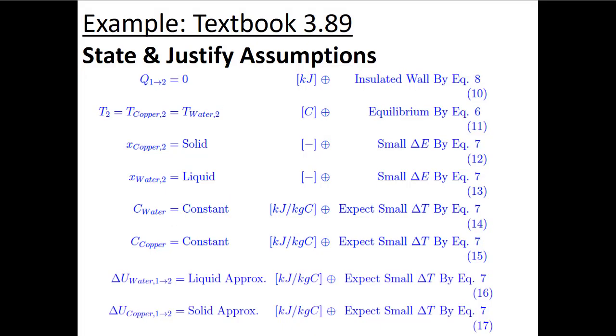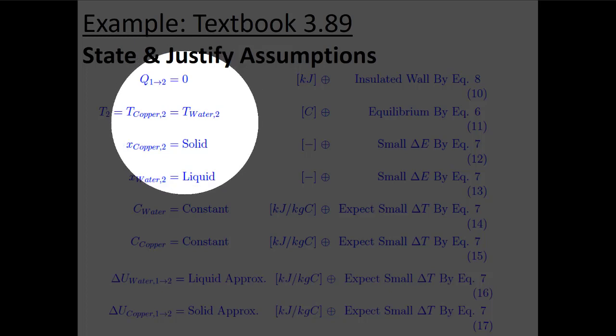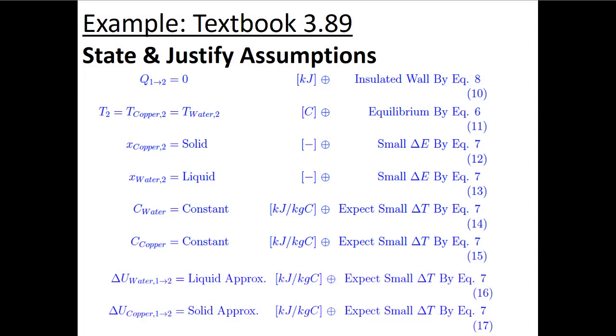So here I'm going to assume that I'm not adding so much energy that I'm melting the copper, and I'm not adding so much energy that I'm boiling the liquid. So I'm assuming that there's no phase change here. And I can go back and check. If my T2 is above 100 degrees Celsius, assuming atmospheric pressure, then my water would boil. And if it's below 0 degrees Celsius, my water would freeze. But here, because we're putting energy in, I'm expecting these temperatures to increase.